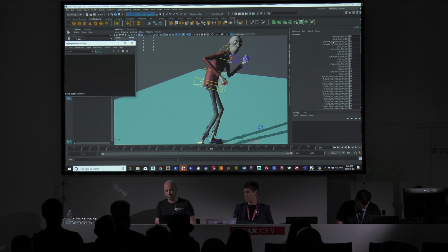If you want to bake it down to something which you can interact with, as far as commercial productization goes today, I would probably use the quasi-static solver, or run it in dynamic mode with your frame rate at like 1 frame a second or something like that, so that the dynamics settle. Then you could bake those out as shapes and add them in as blend shapes into a traditional rig.